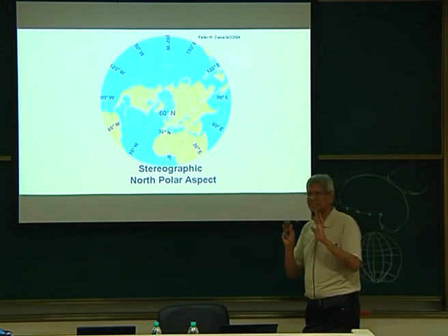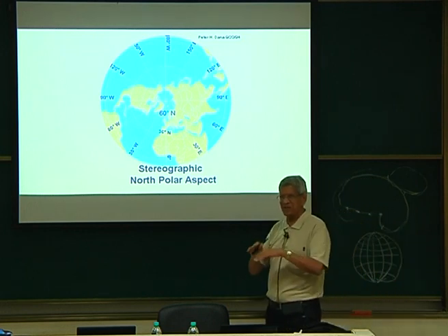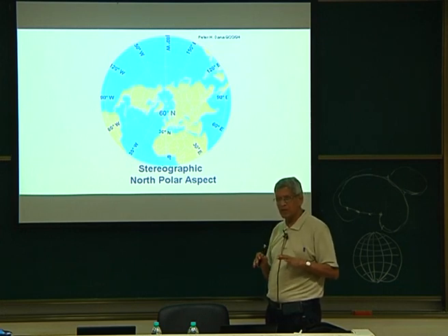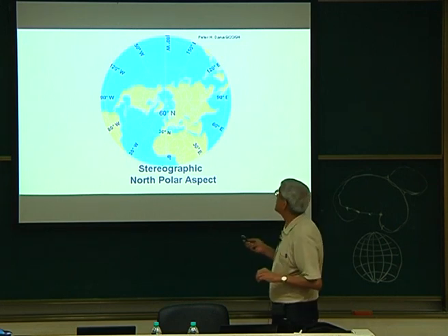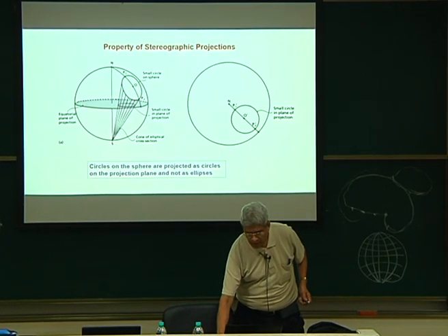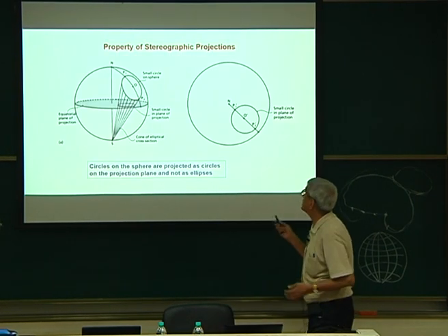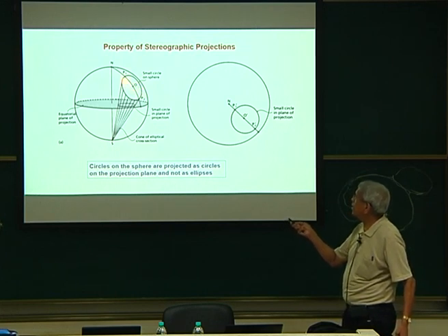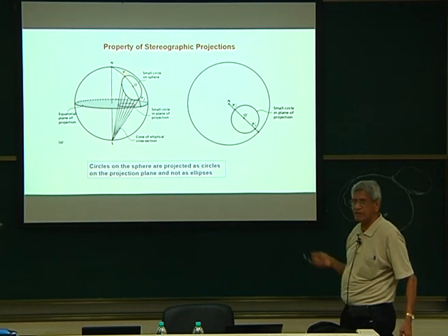Now we know that this is a stereographic projection, where it's a sphere which we are trying to represent in 2 dimensions, so all the angular relationships have to be maintained. That's essentially what is being done. Another important factor is that with respect to any point on the sphere, if you take any pole, all poles which make some angle will generate a circle.